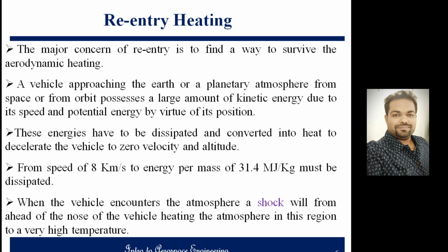The moment it comes in contact with the Earth atmosphere, a shock wave forms in front of the nose, causing a very high temperature rise. As the vehicle plunges into a deeper and denser atmosphere, the vehicle will increasingly be heated by the atmosphere, by developing a layer of incandescent atmosphere around it, while the speed of the vehicle is continuously reduced by the braking force of the atmosphere.